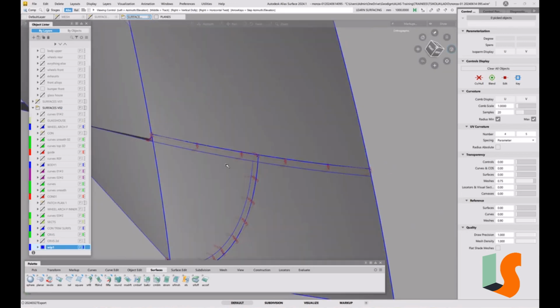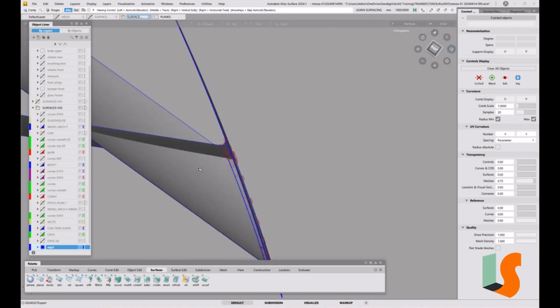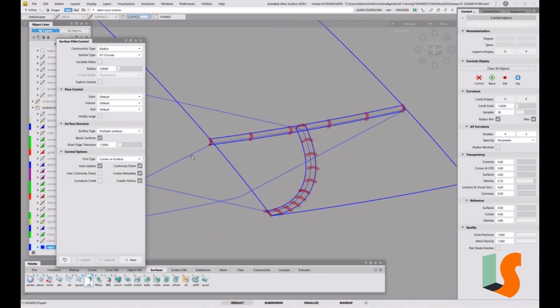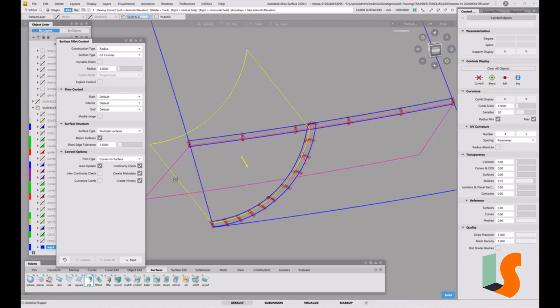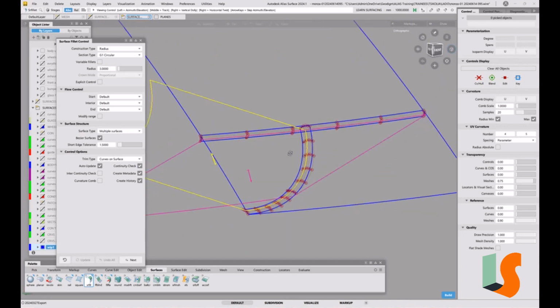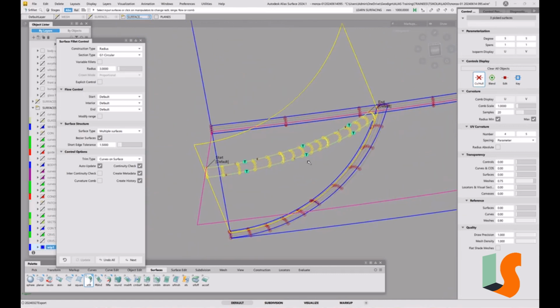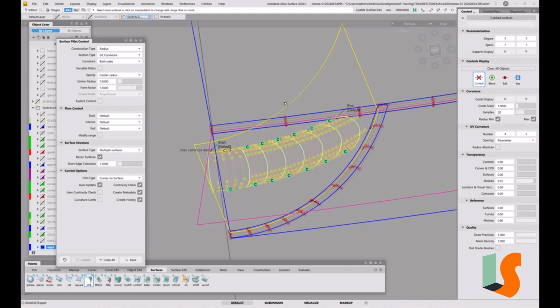So the other thing that we need in here is a fillet inside here. So I'm going to go into the fillet function. This one I will make curvature aligned. I'm going to make sure my normals are around the right way. If in doubt, if you can't see it, sometimes you just have to press the space bar and see what you get. But going around this corner, I don't want G1 circular, because apart from anything else, it's not going to look so good, but it's going to cause more problems with alignment. So I'm going to do that.